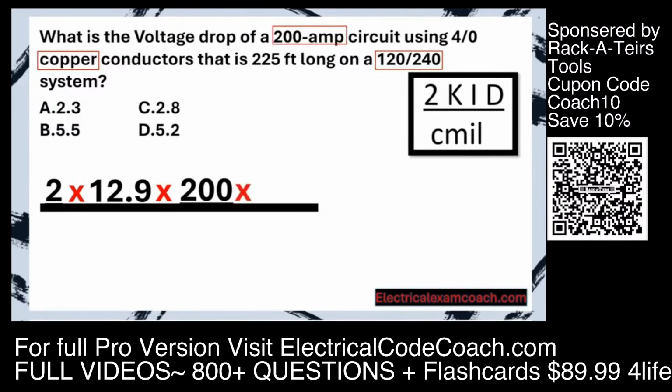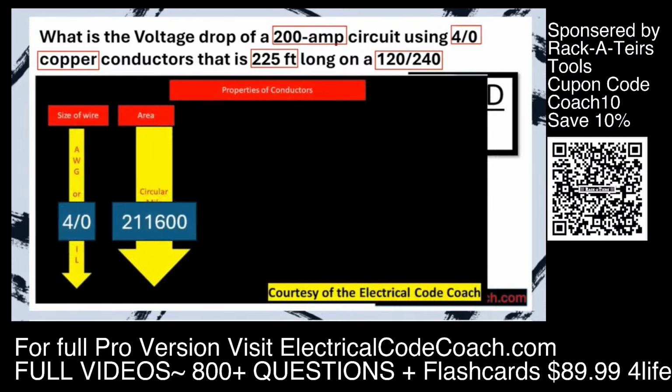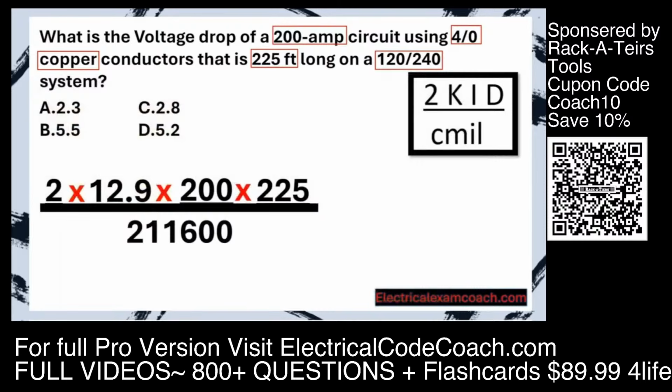Then we put our multiplier, and now we need to look for D. Well, our D is 225 foot, and we put that down. Now we need to find our circular mills. For that, we're going to be looking for 4/0 in the table. When we head to Chapter 9, Table 8, we're going to start on the left-hand side and come down and find 4/0. Then we're going to cross over, and we're going to find that it's 211600. Anytime it's a long number like that, I don't try to figure out my thousandths or tens, I just say 211600, and I write that down. Then I write that down right under here.